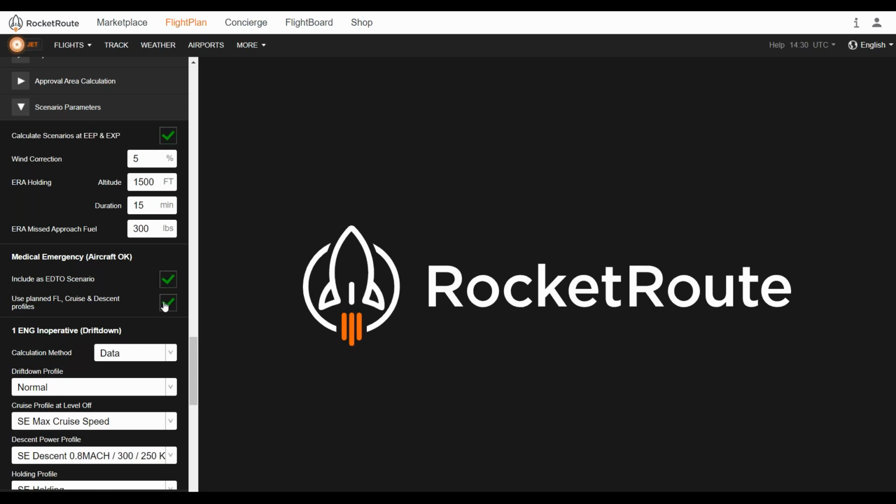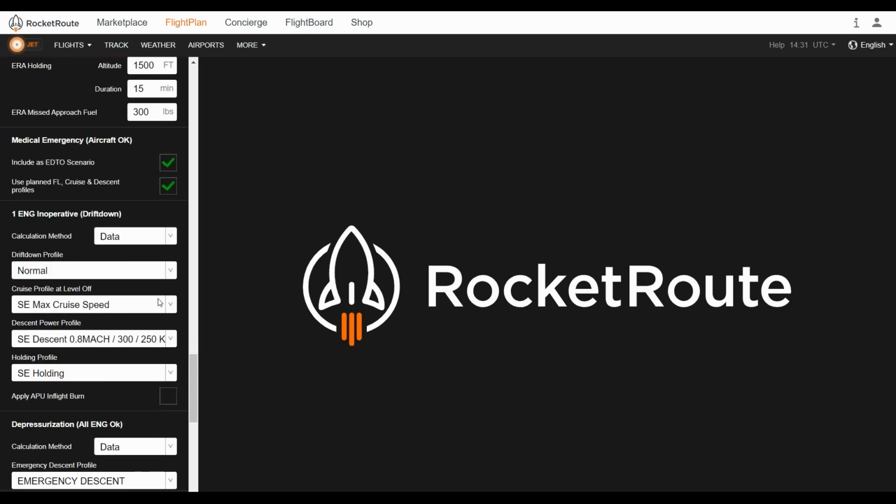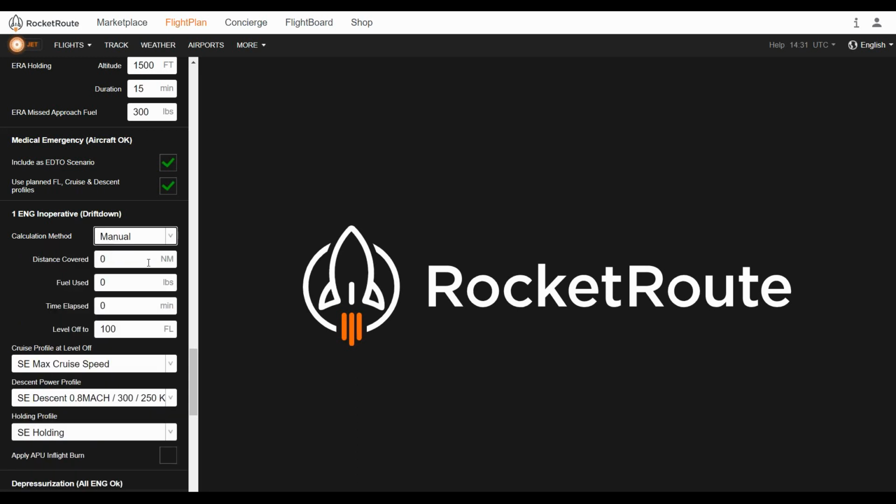The second scenario is one engine inoperative. Here we have a set of settings. First of all, let me start with the calculation method. It can be either data, so the data that is stored in our system will be used for calculation, or it can be manual. I will switch to manual, and here you can see that you have a similar set of settings as in the approval area. You just need to define the drift down settings, and our system will use it as a manual drift down for this calculation. Moving back to data.